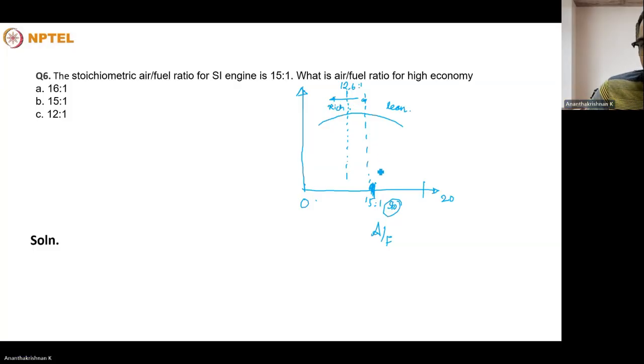So if you use a slightly lower flow rate of the fuel, it will ensure complete combustion and we'll make sure that the entire quantity of the fuel is used. This is based on experimental analysis. If you provide slightly more air, it will ensure complete combustion and we'll be getting better mileage in common parlance.